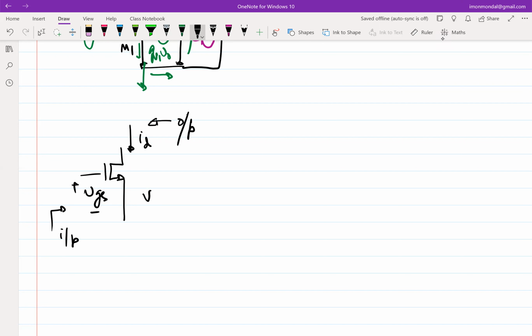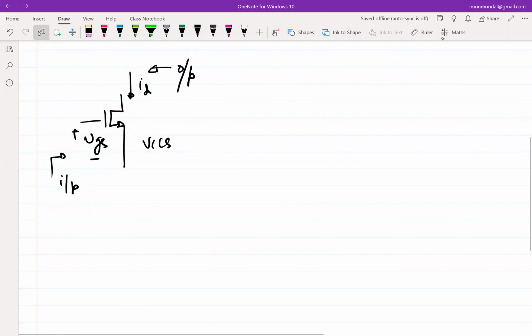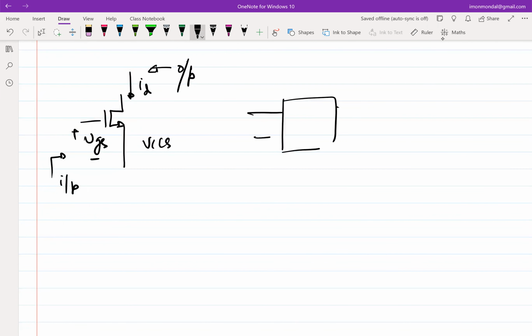This is a VCCS. And in order to figure out whether any contraption, let's assume that I have any contraption, I have an input port and I have an output port. This is input, this is output. What experiment will you do to figure out whether this is a voltage controlled current source or current controlled current source or any one of the four sources?